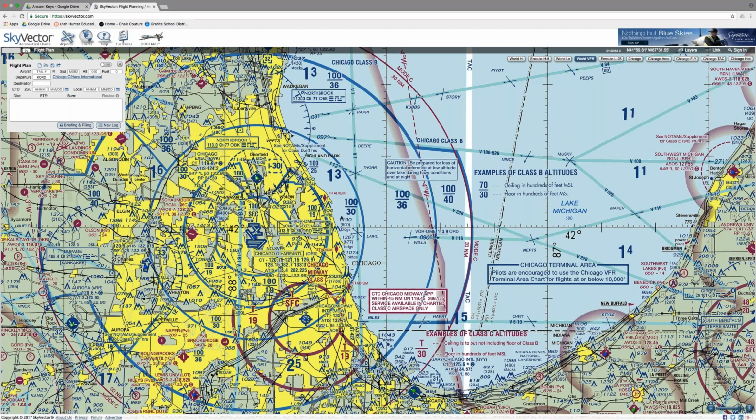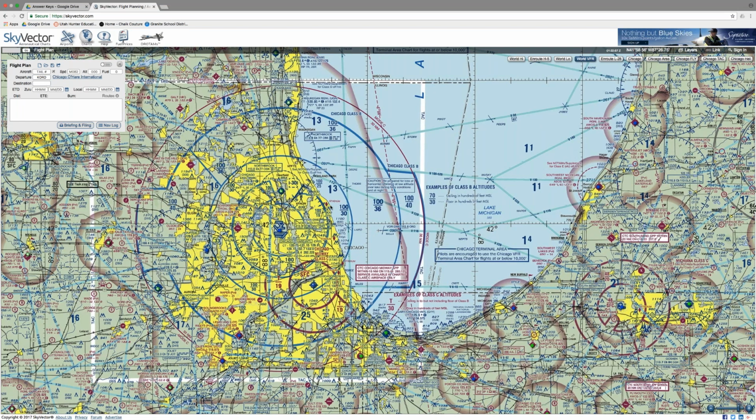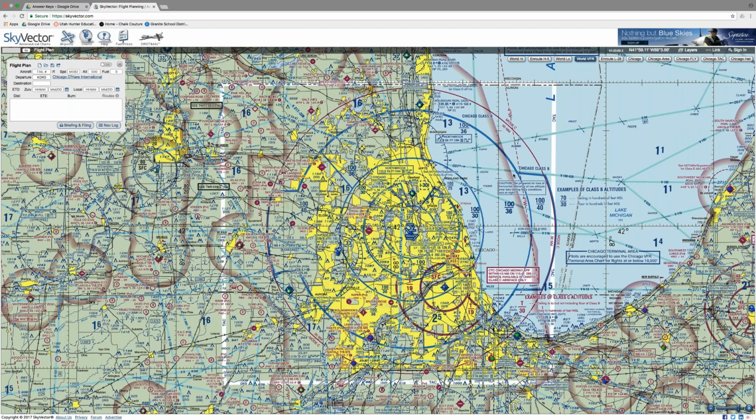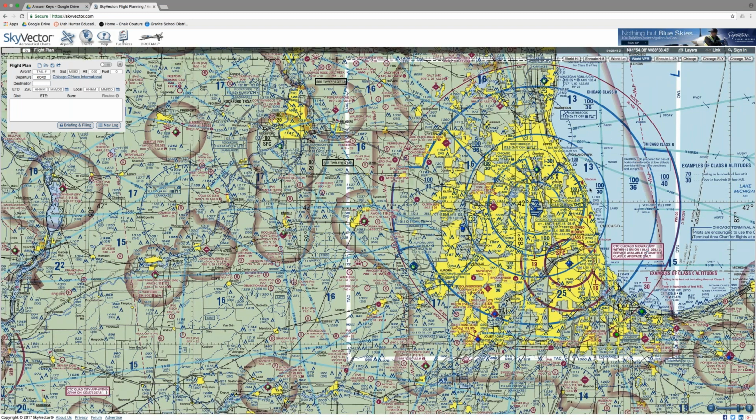So there's other requirements that we're going to go over when we get to airspaces that talk about the equipment on board the aircraft, radio communications that are required, things of that nature. But that's the area. Underneath would be 200, but if I'm in that ring, if I'm, say, at flight level 040 or 4,000 feet, then I'd be restricted to 250 knots.